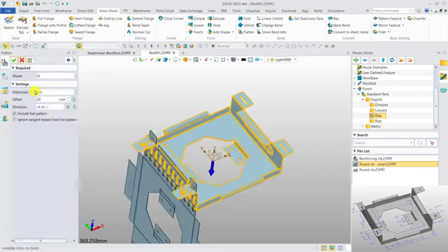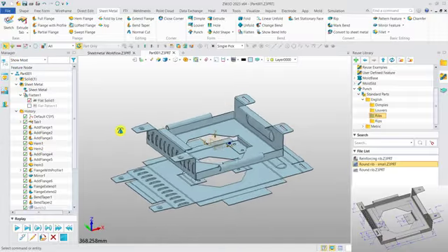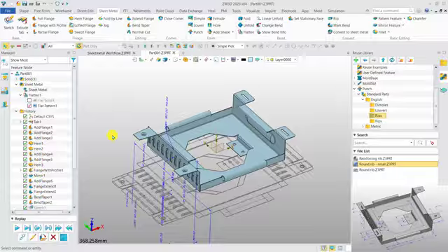Okay, maybe we can redefine the direction to see it more normal. Direction, we can choose the negative of the z direction, and the offset, stationary, all clear. We can click OK. Okay, so this is the flat solid, also the flat pattern.